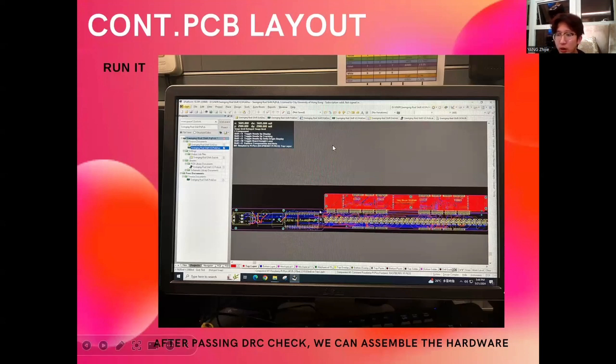And the auto routing of the PCB board: the routing step transforms your air wires to board copper tracks. It is this step that allows you to make your board functional. You can use the manual or auto routing capability to complete the process.